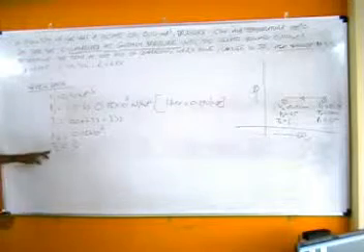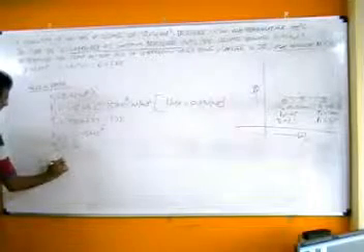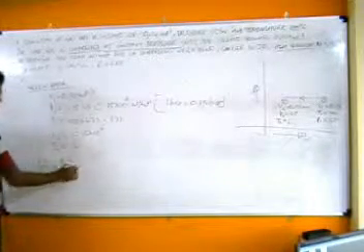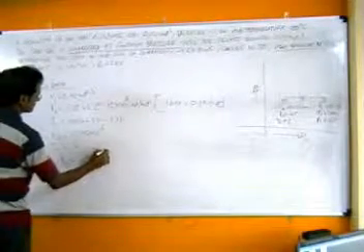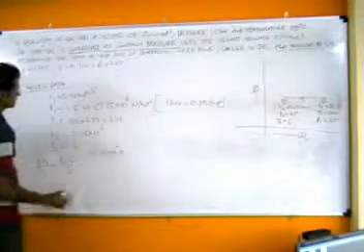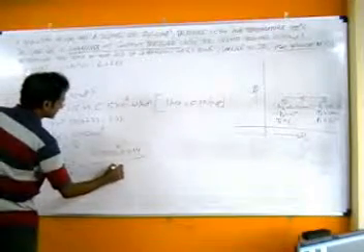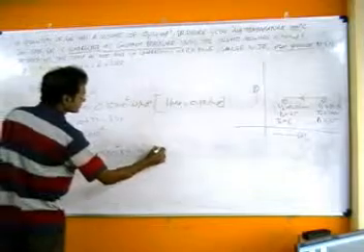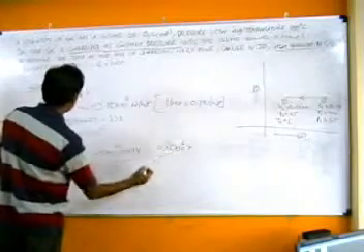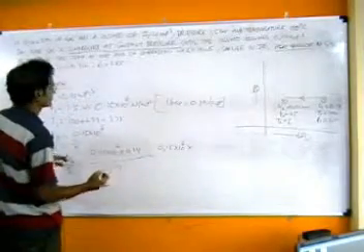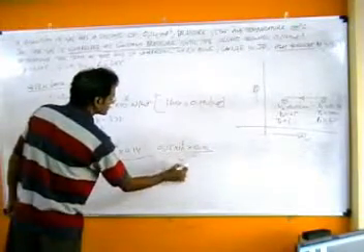So if we have to find the value of temperature, we use the standard PVT relationship and substitute the values to get the value of temperature. Therefore P1 is 0.15 into 10 to the power of 6, into V1 is 0.14, by T1 is 373, equals P2, same, and the volume V2, the volume is compressed to 0.112, and the temperature is what we have to find out.